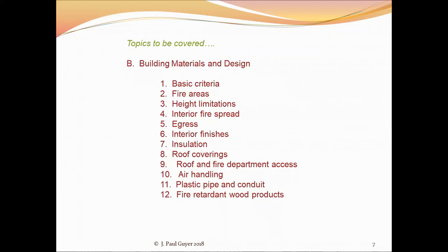And of course, that space also can be used for conduits and ducts and things like that. But since this is now part of the air handling system, all of those kinds of things that you might put in the plenum space above the ceiling, like pipes and conduits, need to be of non-flammable materials. So no plastic, that sort of thing. Same thing with the electrical distribution system. The insulation needs to be non-flammable.